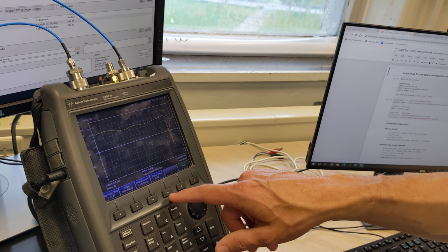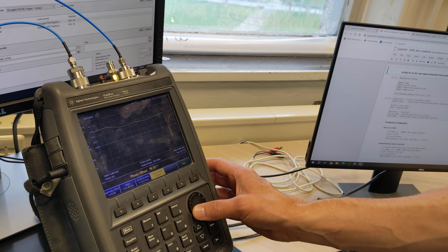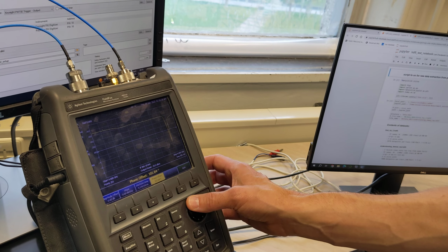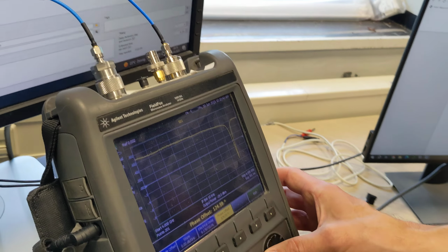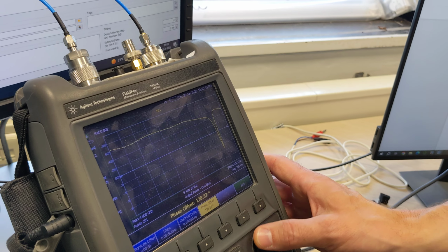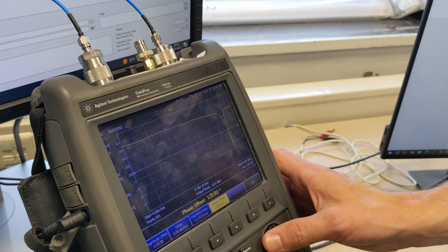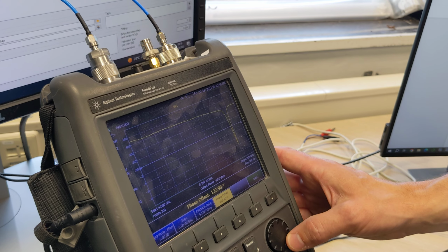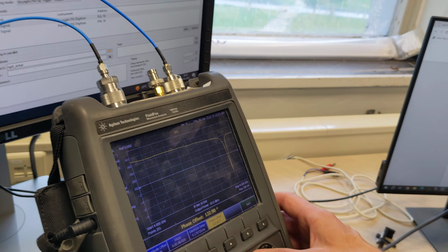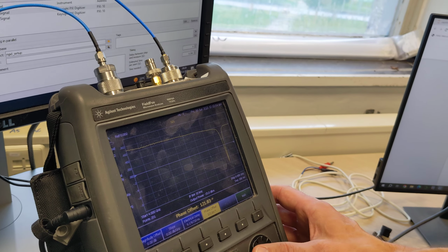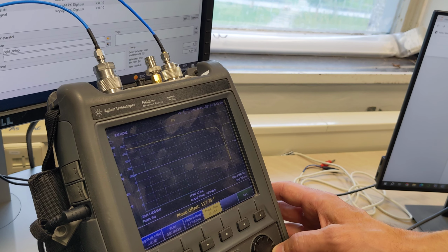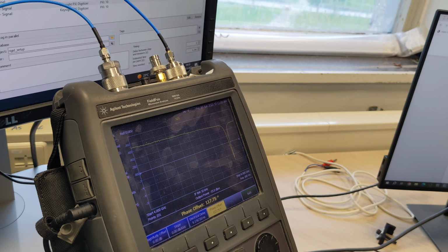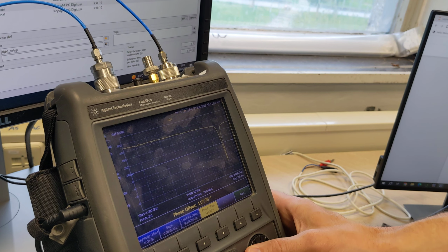Looking pretty good. In fact, now I can, in principle, use this knob, right? You can see it's getting more and more symmetric, and I've gone a little bit too far. It's asymmetric the other way. So the point, I'm going to guess, is about right there. And now my real part, maybe a little bit further. So you can see the offset phase I've needed on top of the electrical delay is about 117.75 degrees.